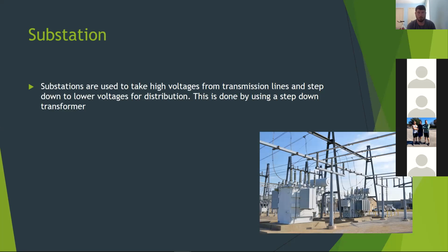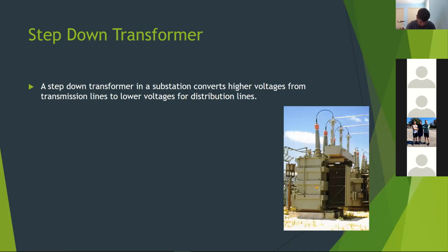And in our substation, basically you're going to use a step down transformer to take the higher voltage off of the transmission lines, and the output should be a lower voltage that you can easily send through neighborhoods and to businesses. And with that, you're using your step down transformer. On the picture there, you have your higher voltage coming in from the left, your lower voltage coming out the right as you step down, to your typical distribution voltage there. Okay, you want to rephrase that again as far as your left to right? Your higher voltage should be on your left, right? With the bigger bushing.